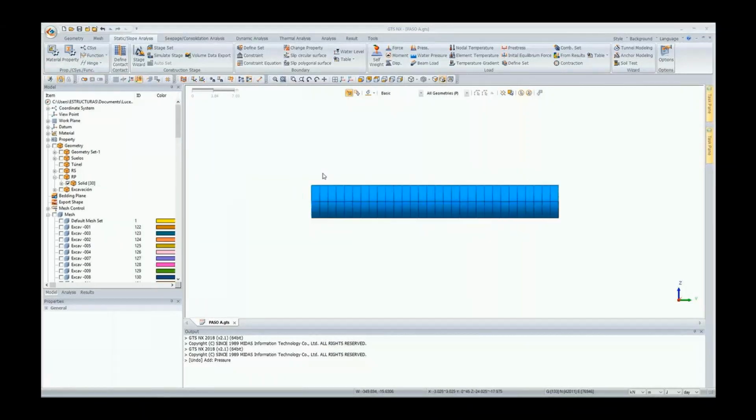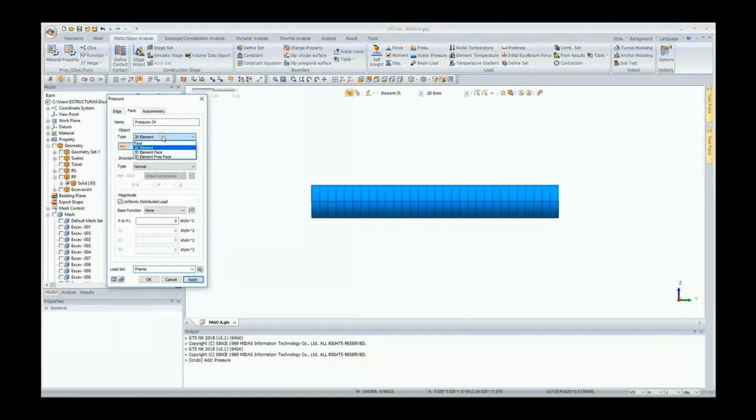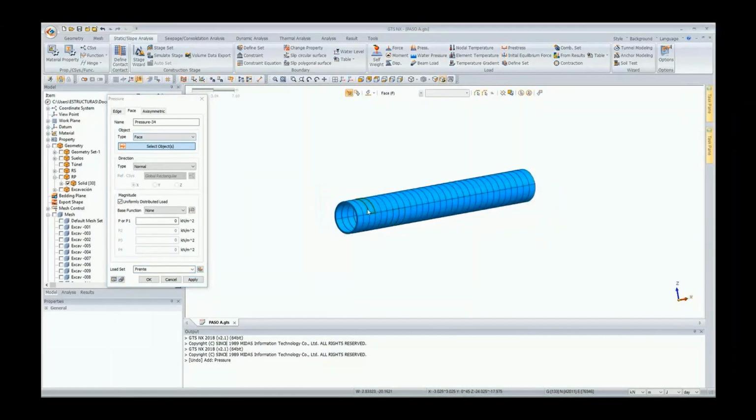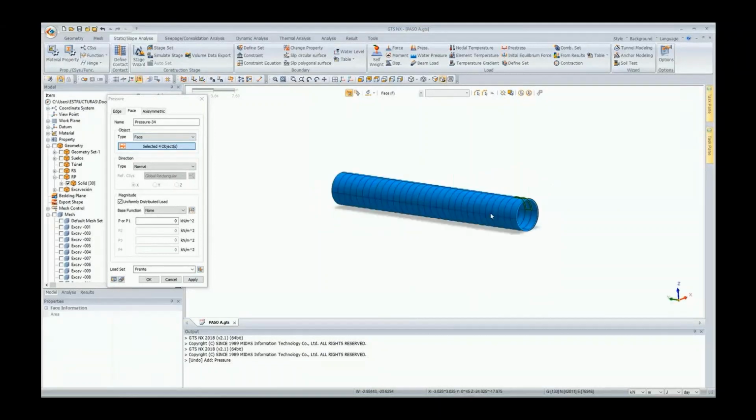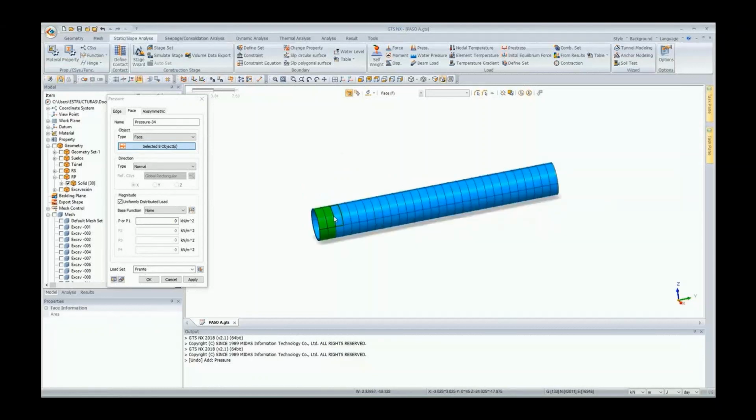This might actually be a little easier to do on the geometry. So I'm going to now select, instead of selection type, faces. And I can select the outer faces of the rings. Since we are advancing 3 meters each time, again, we select 2 rings at a time, 8 faces total. And we have selected all the outer perimeter. And now we apply again this radial pressure load of 265 pascals, and this is under the radial load.